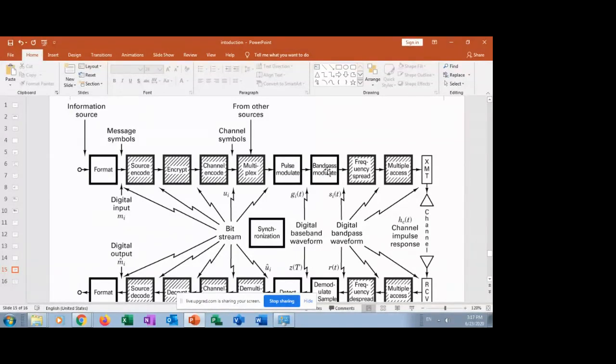After that, this is a security part, after we have the band pass modulated signal. Keep in mind, the band pass digital modulated signal is an analog signal, not a digital signal, because the carrier is in analog format and the information is in digital format. So it is a combination of digital signal plus analog signal. After converting into a band pass signal, amplitude shift keying, phase shift keying, and frequency shift keying are analog signals, not digital signals. Keep in mind, this is very, very important.